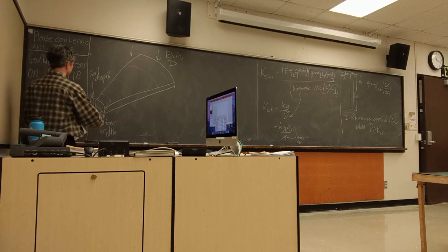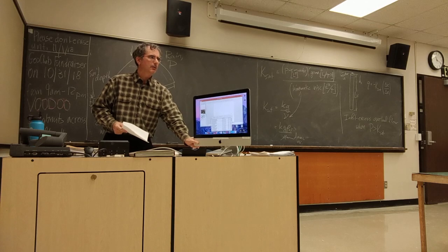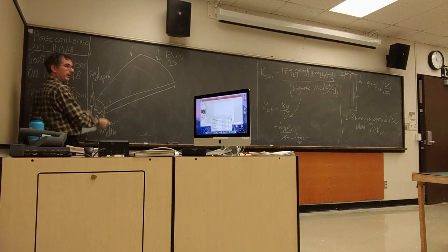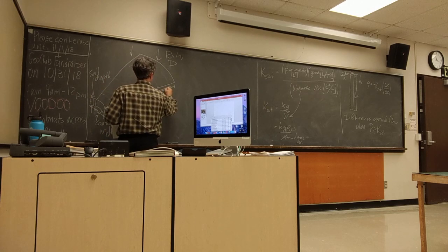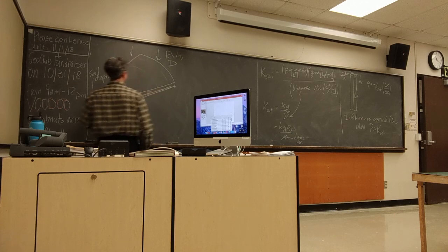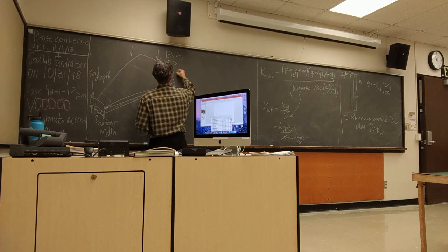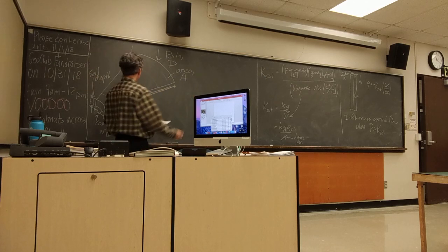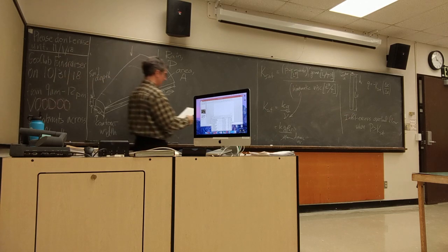And let's say, for argument's sake, that I've drawn this to represent the place where I start getting saturation overland flow, so that my water table is at the surface just right here. Any water table I've got hits the surface right there, but in general goes to 0 at the divide up there. Okay, so there's my water table. I've got an area, and a slope angle.